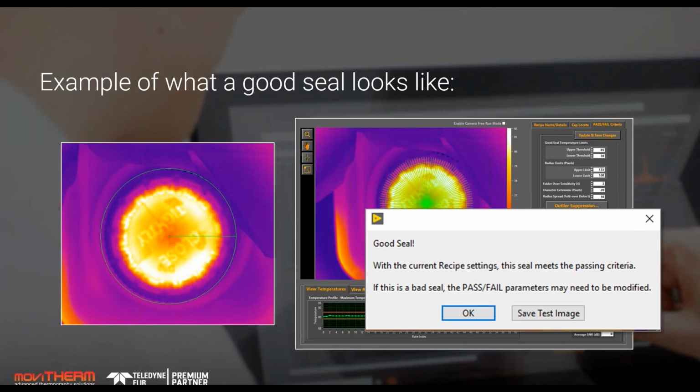Well, if you have a cold spot there, a lot of the times it could be underheating. Liquid on the seal can be a problem, and that usually will show up as a bluer area. Sometimes some of those seals have a little tab that folds over, the ones you can get with your finger to pull off the seal. Some of those little tabs act as heat sinks. But typically it's areas that aren't bonded very well.